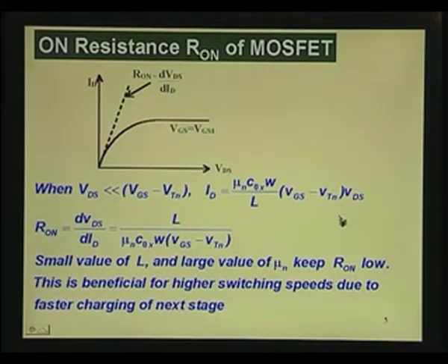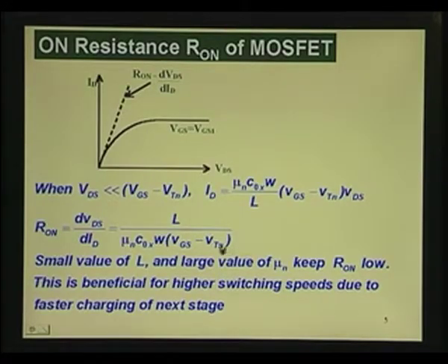That is the resistance, and that resistance is inverse of this quantity, which actually is proportional to length, inversely proportional to mobility. Very clearly, you must reduce the channel length, and also carrier mobility should be high. Other parameters of course are the oxide capacitance and all. It goes without telling that those should be larger, but you can't tolerate large oxide capacitances. So, do not try to maximize oxide capacitance, maximize this quantity, maybe this voltage can be increased.